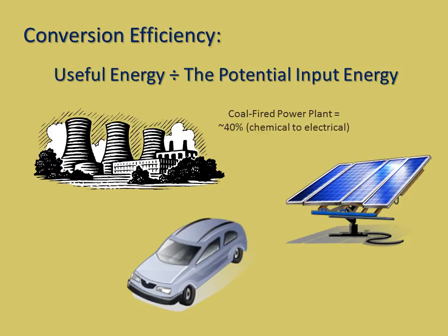Another example, as we mentioned just a moment ago, is photovoltaic technology. And photovoltaic technology converts solar radiant energy directly into electrical energy. So the potential energy striking a solar array, the percentage of that that's converted into electrical energy is roughly 18%. It varies depending on the type of photovoltaic technology that you're using. Anywhere from 11%, and the highest photovoltaic modules achieve conversion efficiencies of 20-21%.